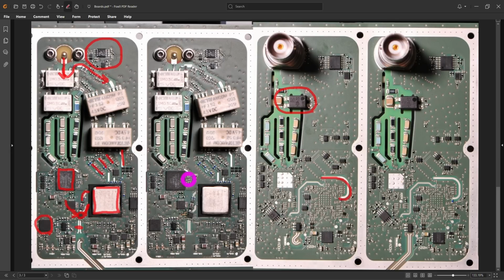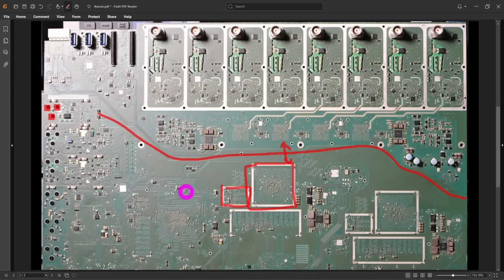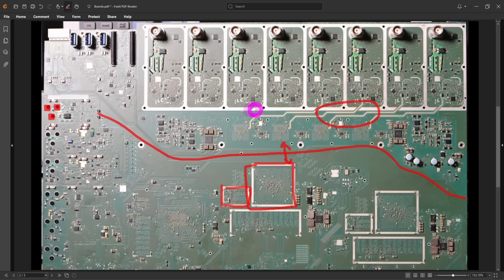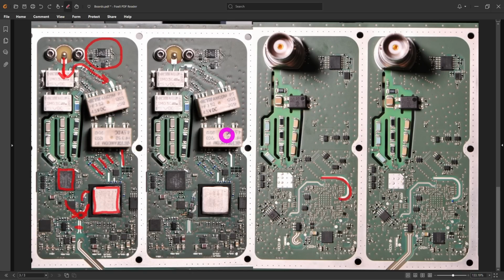Now if you look carefully, because some of the channels are routed to the ADCs on the front side of the PCB and some on the back side of the PCB, like for example these ones are on the back and then these ones are in the front, they don't arrive from the same side, so you have to compensate for that. And this is a very subtle point here. Let me see if I can show you. So up to this point things look the same, but then this guy is on the top of the board, and it goes through two sets of vias to go down and then back up unnecessarily, but it has to do that in order to match the number of vias between all the channels, so everything is completely matched.